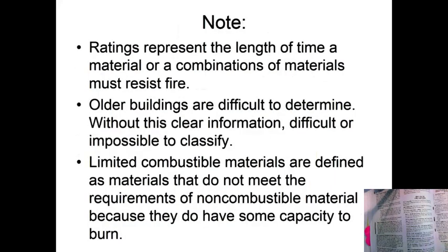All right, so to kind of summarize, ratings represent the length of time a material or a combination of materials must resist fire. Older buildings, remember, are difficult to determine without this clear information, difficult or impossible sometimes to classify. Limited combustible materials are defined as materials that do not meet the requirements of non-combustible materials because they do have capacity to burn. So, hopefully this kind of clarifies some things, and if you've got questions, make sure you get with me.